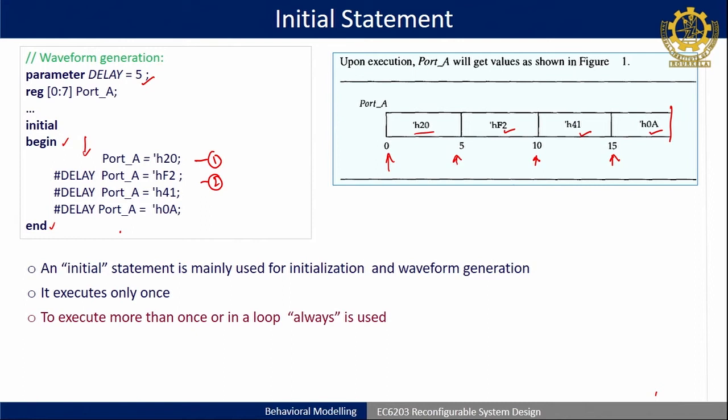As initial executes only once, using initial we can't generate hardware like combinational design or sequential design. That is why, to execute more than once, always is used.